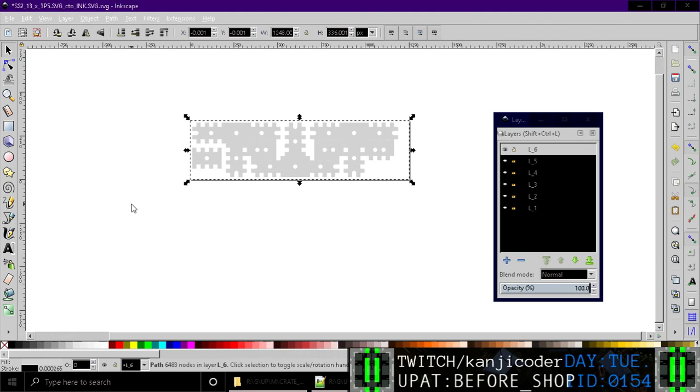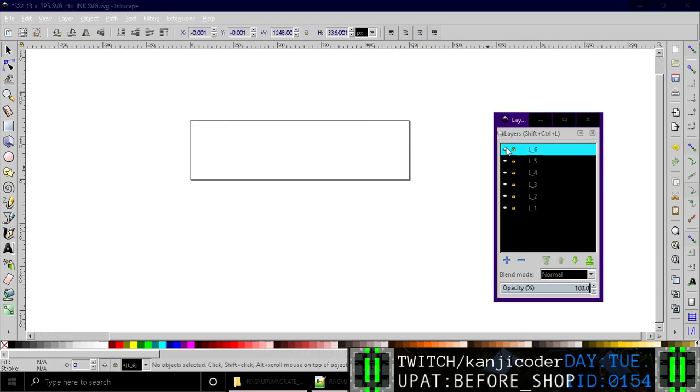If you're curious, this is for 1/8 inch thick acrylic. For 1/8 inch thick acrylic, if we do 6 passes at 80% speed and 100% power and a frequency of 4,999 hertz, we get pretty good results.